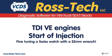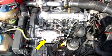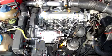There are several generations of TDI engines from Volkswagen and Audi. The older TDI engines with an external injection pump and mechanical injectors are in the VE class of TDI engines. The engine control module can adjust the pump, advancing or retarding the injection timing. When you set the start of injection, you are making sure the pump is mechanically set to a middle position so the engine control module has full advance or retard adjustment of the timing as needed.